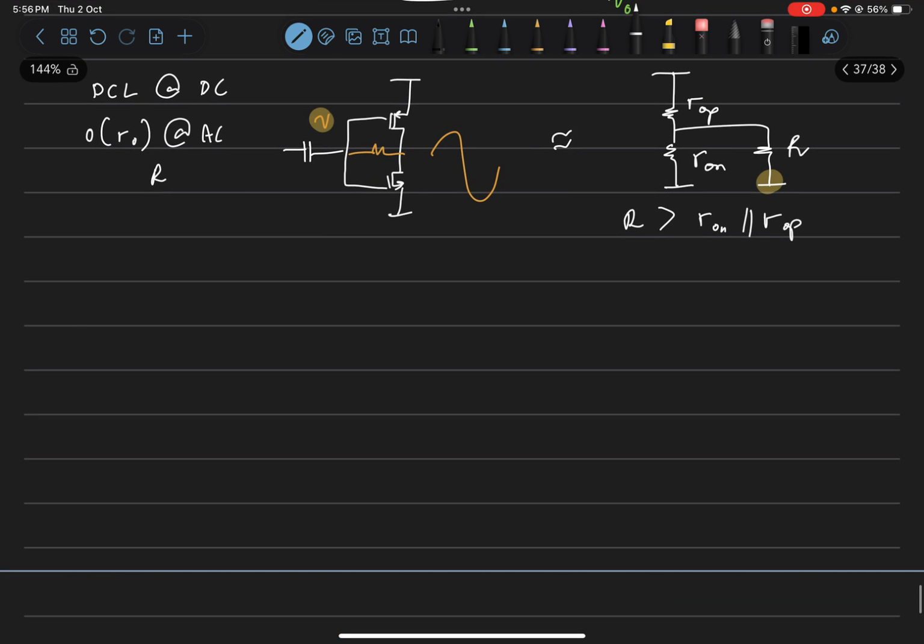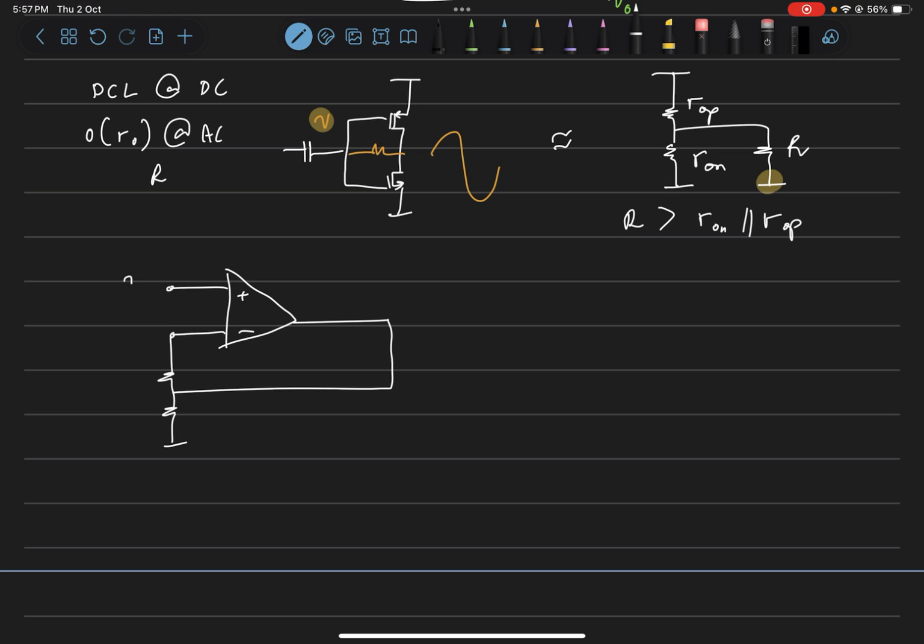Now a similar case can be seen when you wish to calculate the gain of an op amp. Biasing is not an issue when the op-amp is in feedback. Let's say you have a non-inverting amplifier in unity feedback, and the DC value here is Vi naught.